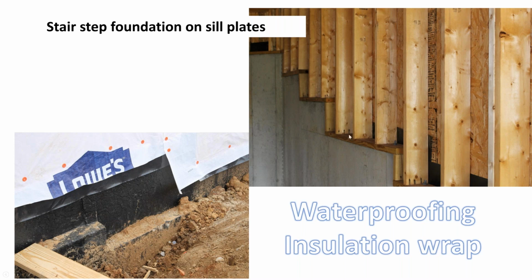And this is typically where they start, because the sill plate is usually really close to ground level. The problem lies with the fact that if you have a sill plate and somebody keeps adding mulch to the foundation and it gets above the sill plate or above the brick line, it's just dirt up against that sill plate. It's an invitation for the termites to come right in. Okay, so technically you're supposed to keep your mulch and your dirt a couple of inches below where that sill plate is going to sit, so that you alleviate that problem.